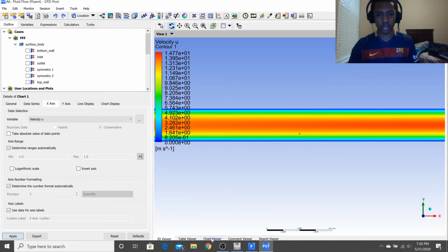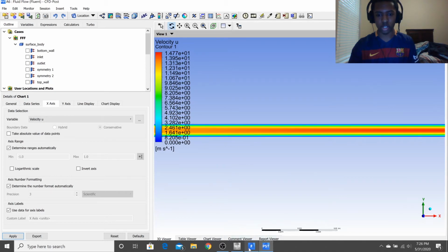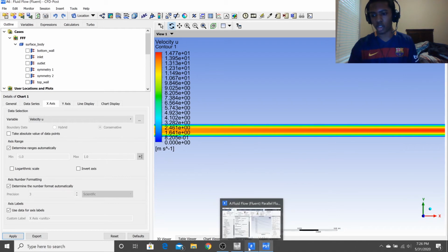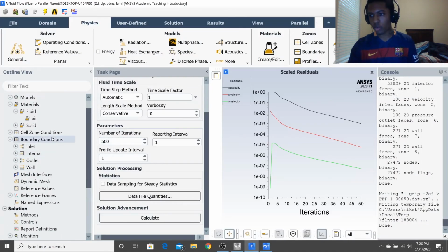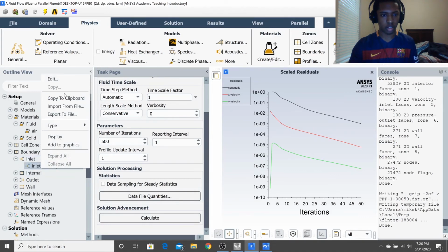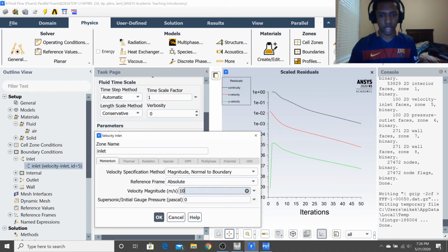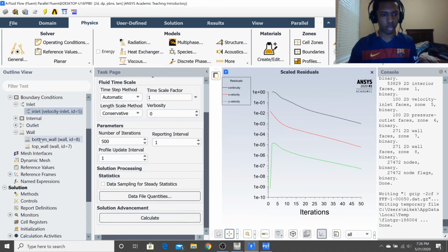And now that we have this set up, all we have to do is go change our flow conditions, and we can see the same results for Couette and hybrid. So let's go back. For Couette, what we want to do here is change the inlet, have a velocity of 0.5, and we'll want to change the top wall.